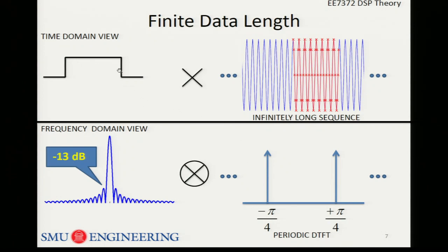And so that's the intuition. Hopefully in your mind you can think, well, the wider I make this window, the narrower I can make my frequency spectrums for the signals. And you can, except that as an engineer you're going to find out that making this window wider means you're taking more data, or you're spending more time taking data when you could be spending more time taking data somewhere else. So there are going to be trade-offs involved in all this.